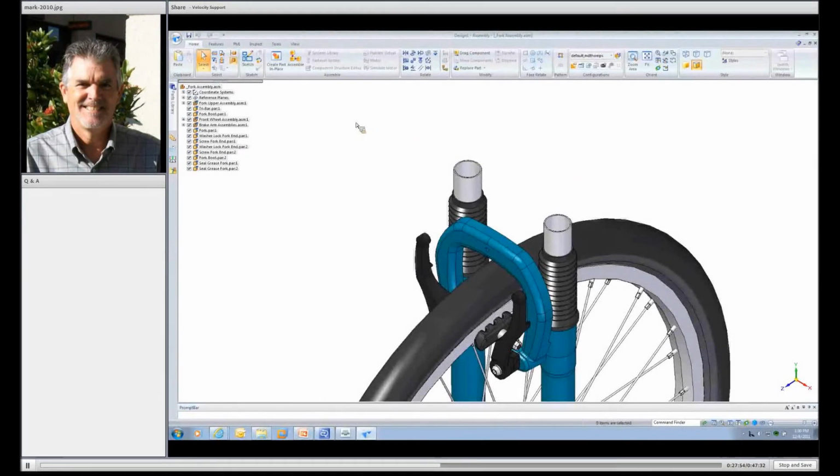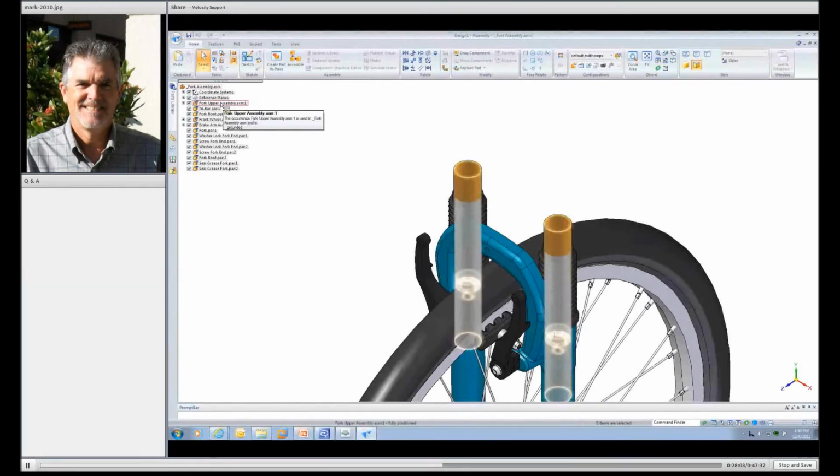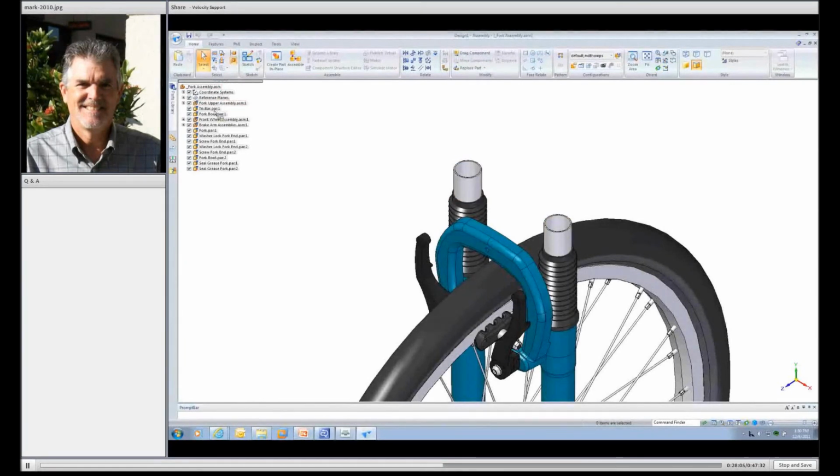I'm going to zoom up a little bit. You can see I've already included the top faces for this particular design. And I'm just going to come up to the sketching tools, or my draw tools, and pick the circle by center. And you'll notice that before I start drawing anything, what I want to do is lock to a reference plane. Now notice the crosshairs on my cursor.